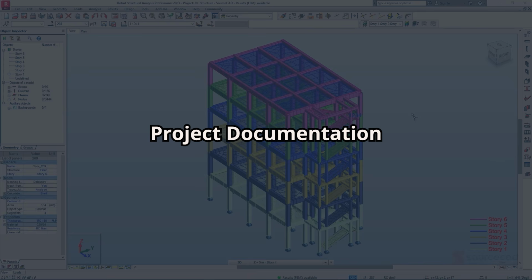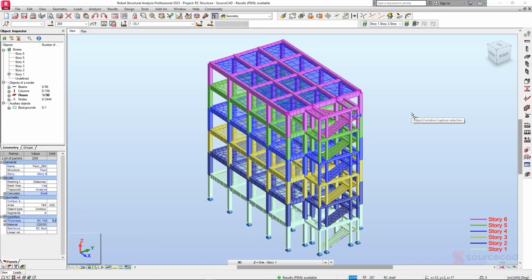Okay, so now that we have designed the structural elements, it's time to create the detailed reinforcement drawings and also to generate the necessary construction documents. So these documents will provide all the essential information for the construction phase, and it's quite easy to get it. So you can simply navigate to this print, and you can print maybe this specific drawing. But even better, you can go to the print out composition.